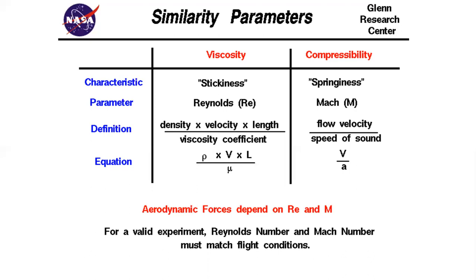When you change pressure, you change density and viscosity, and there exist wind tunnels that can change the pressure of air. Some experiments are done with air pressure higher, some with pressure lower than atmospheric. This wind tunnel is called a variable density tunnel, and we talk about this wind tunnel in next hour's lessons.